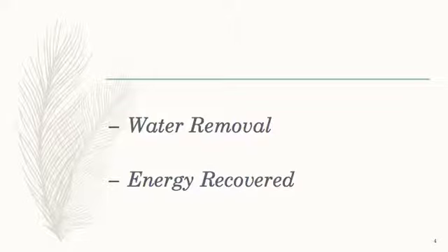So the choice of sludge treatment methods depends on the volume of sludge generated and a comparison of the treatment costs. Energy recovered: energy may be recovered from the sludge through methane gas production during anaerobic digestion, or through the incineration of the dried sludge, just like the drying bed of the sludge, which I have already explained in my previous lecture about tanneries.